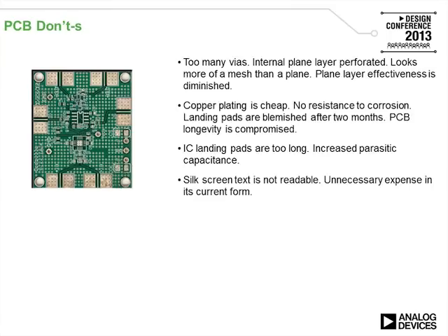Longevity is compromised. IC landing pads, notice the middle has an IC. They are very long. This will increase parasitic capacitance, and frequency of operation is reduced. Another thing to note here, there is silk screen, but it's not readable. This is really an unnecessary expense. If they can't read the silk screen, it has no purpose.